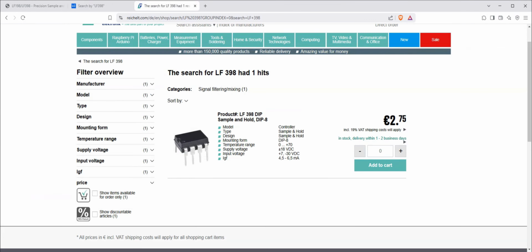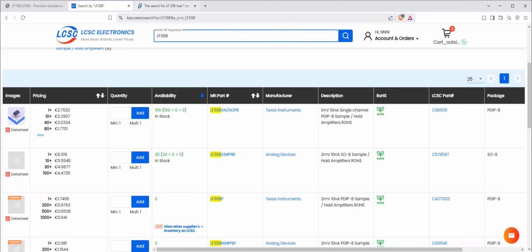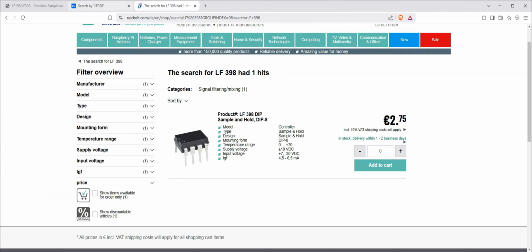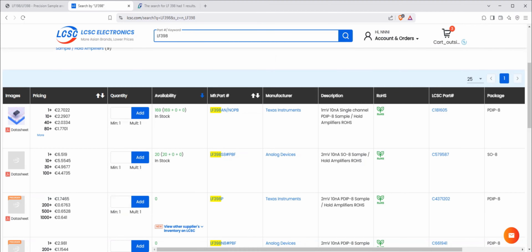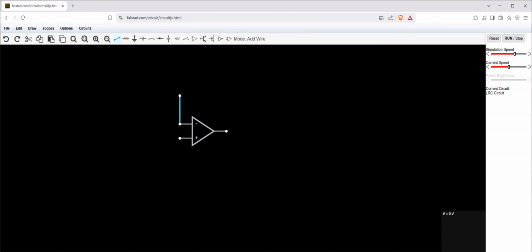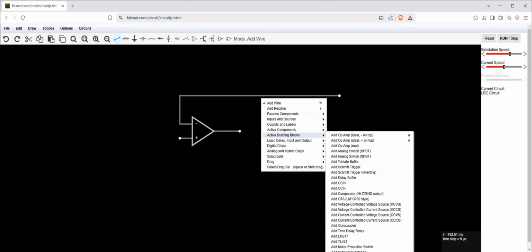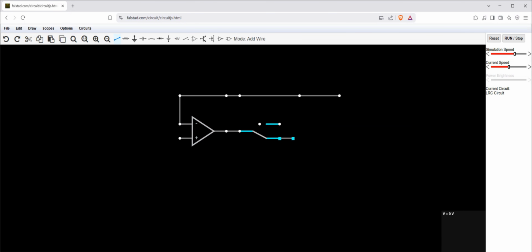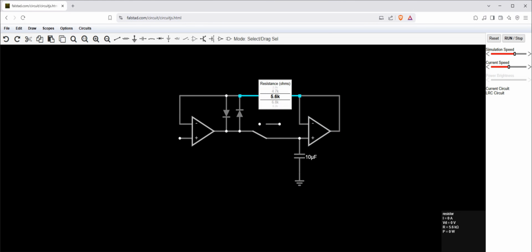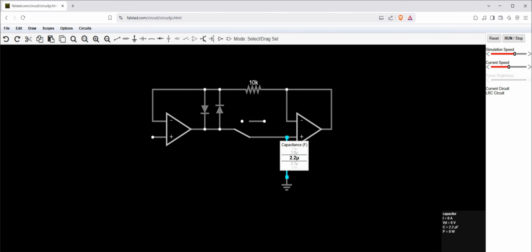It would be arguably easier to just buy the chip, but before investing in a rather expensive and borderline obsolete component, I would like to test the basic functionality using the parts I have on hand. The discrete sample and hold circuit consists of an input buffer which wraps around the analog switch, sample capacitor, and also the output buffer, basically nullifying its offset error. A pair of antiparallel diodes prevents the input buffer from going open loop when the sample switch is opened.